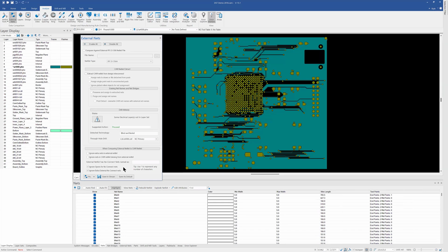Now, out of a lot of CAD systems, they'll have what's called no connects or dummy nets. This is one of the recommended ways of identifying those nets, because you don't want to do a full test on them. They're just single point nets or surface mount pads that don't connect to anything, or fiducials. Sometimes I've even seen non-plated holes in here that whatever CAD system outputs as a single point net. Anyway, so that we don't have a big, huge list of failures for those, you would identify them here.